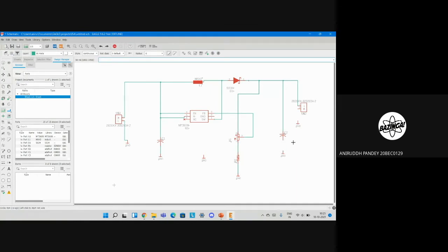Oops, that didn't connect. Okay, now instead of directly connecting the wires, there's another way to connect the two terminals. I'm going to show that. Just place a wire, double click, it will end it over here, and place another wire over here. Just double click, end.